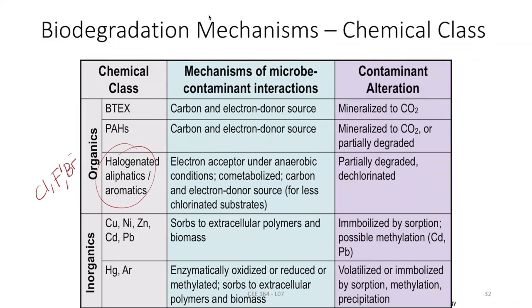They receive electrons and become chlorine gas or fluorine gas. So reduction can occur if you have fluorinated or halogenated organic pollutants. If you have anything else like BTEX or oil, they are oxidized. So that means you can add oxygen or electron donor. But if you are looking at a halogenated compound, you need an electron acceptor.